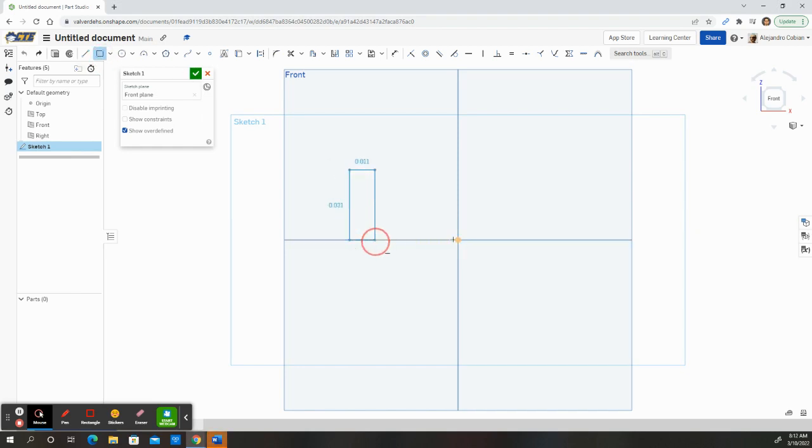So let's say we don't make a perfect rectangle like that. All right. Now we can do a relationship. Let's click on this. Nope, not coincident. We want to click on midpoint here. So click on midpoint, this line, and then the dot, or our origin, and we actually center the rectangle. All right, we don't care about the dimensions right now.